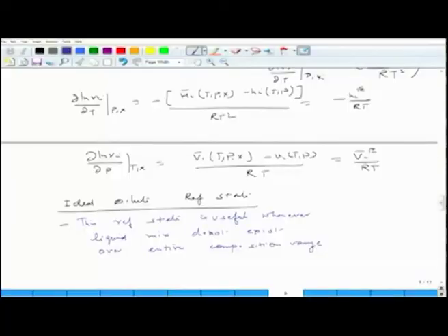So, by considering a Raoult's law sense, which essentially is valid when the system remains in a liquid phase from 0 to 1 composition, then in that case you have to come up with a kind of fictitious reference state if you want to use Raoult's law as a reference state from the Raoult's law sense. So, we need to change to a different reference state, and that is where the ideal dilute reference state comes into the picture. So, as I was saying, if you consider a liquid